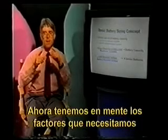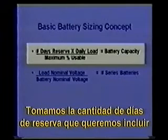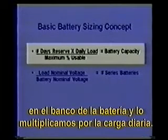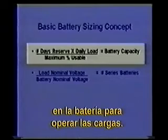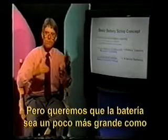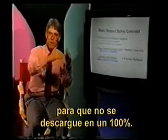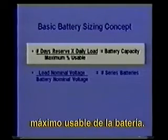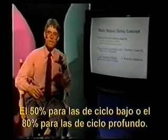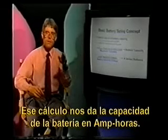Now we have the factors in mind that we need to actually calculate battery size. We take the number of days of reserve that we want to build into our battery bank, 4 days, 7 days, 10 days, and multiply that by the daily load. That, at first glance, would give you the amount of energy you need in the battery to run your loads. But we don't want our battery to be just that size. We want it to be a little bit bigger so that we are not 100% discharging our battery. So we divide that product by the maximum percent usable from the battery, the 50% for shallow cycling or the 80% for deep cycling batteries. That calculation will give us the battery capacity in amp hours.